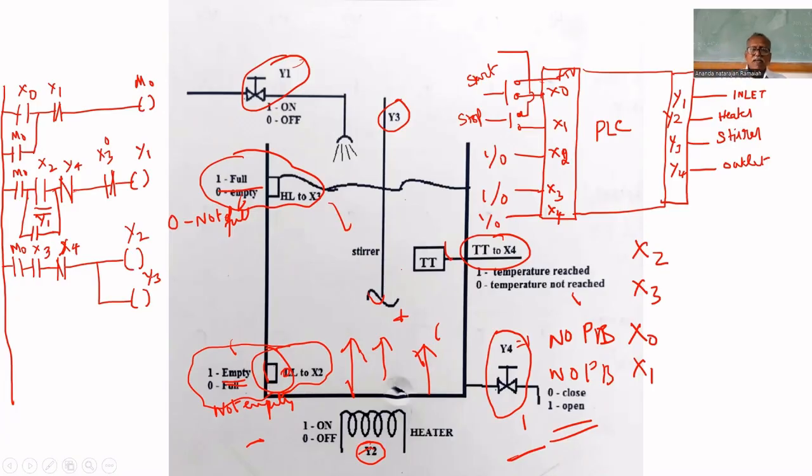In 2 ways we can operate the heater. One is we can keep the temperature at the required level, then turn off and keep for 100 seconds or 200 seconds, then we can drain. That is one way of programming. Another one is you want to keep the temperature at the set point, which means if the temperature falls below that set point, the heater has to be turned on again, so we have to include that also in the run.